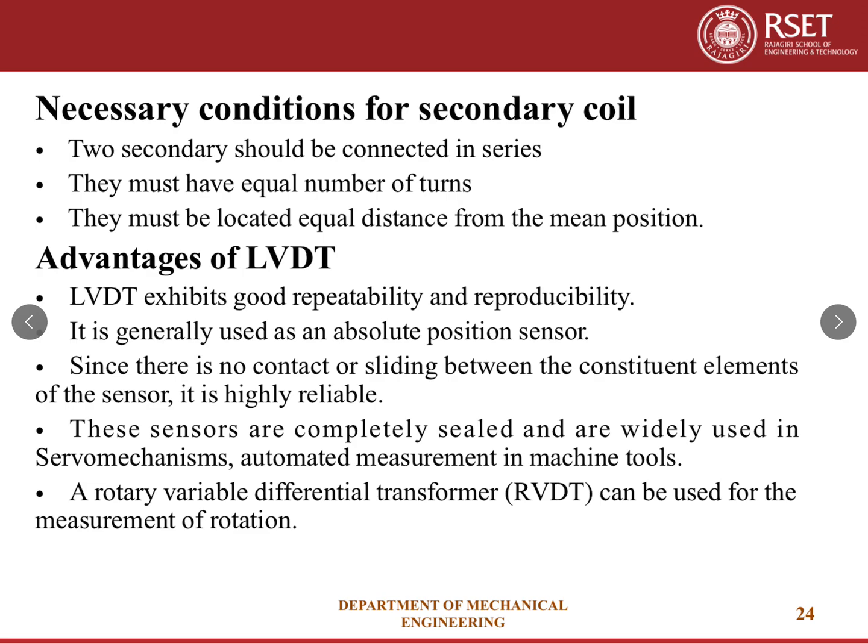There are certain necessary conditions for the secondary coils. These two secondary coils should be connected in series, not in parallel. They must have an equal number of turns. They must be located at equal distance from the mean position. So: equal number of turns, equal distance from the mean position, and connected in series. That's the condition. Next is regarding the advantages of LVDT.